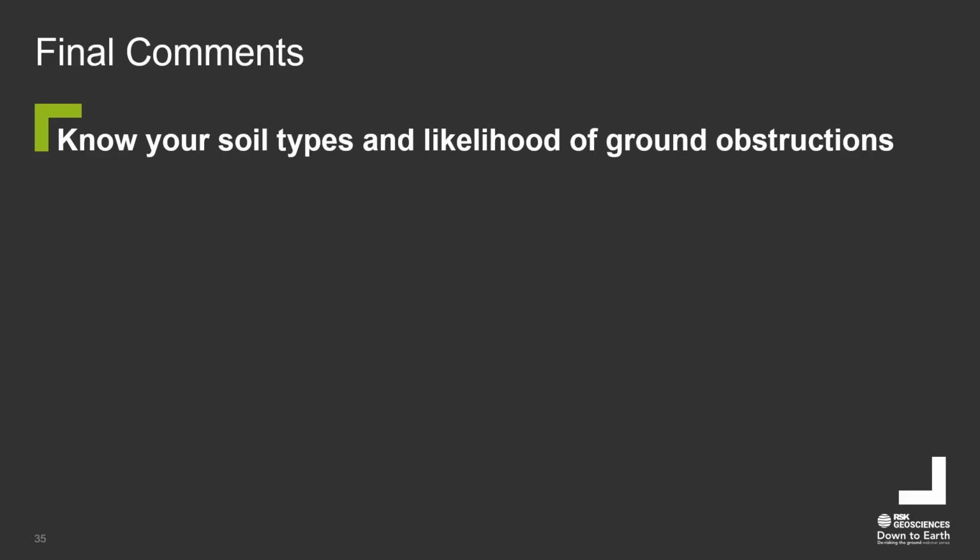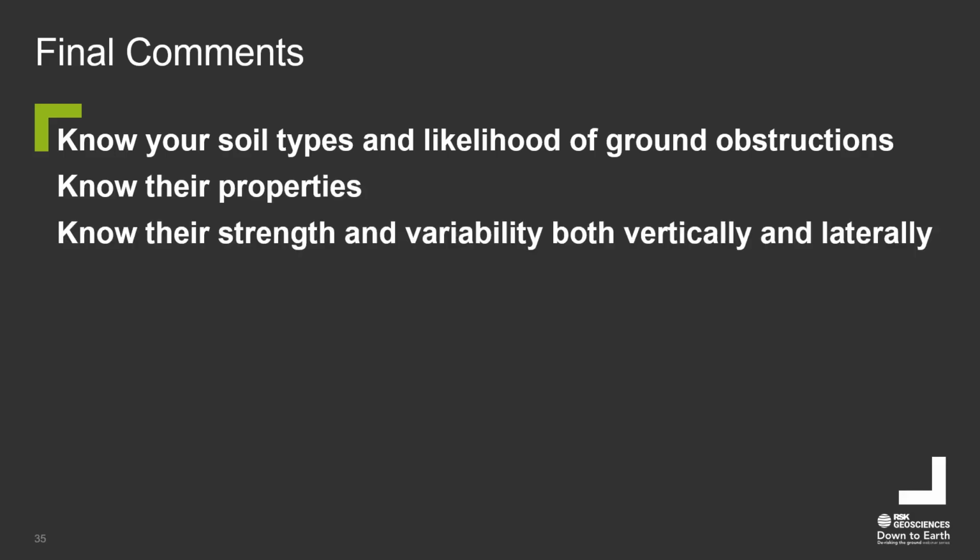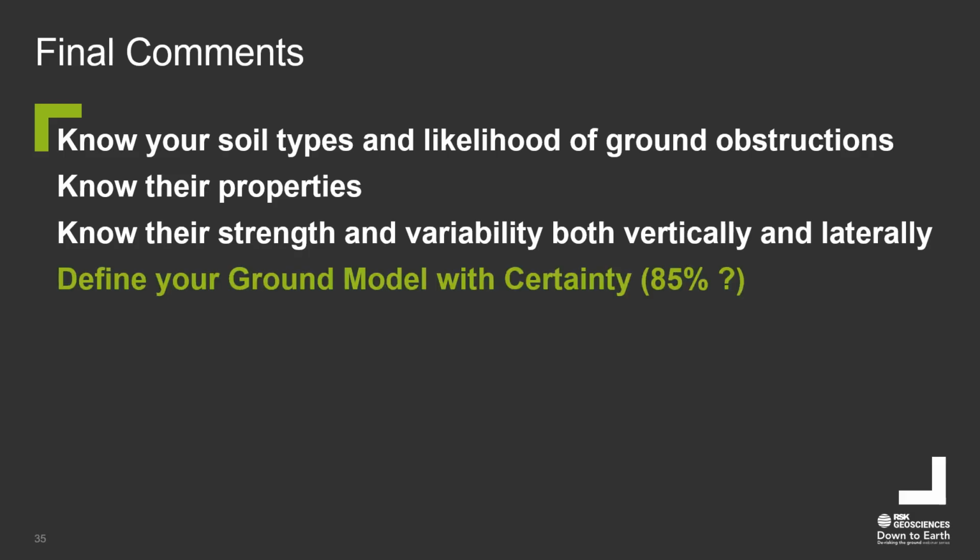Obstructions in the ground are crucial as well with ground investigations and ground improvement techniques, because obstructions will cause big problems for your site ground improvement techniques. Another aspect is properties and details, so we're looking for their strength, variability, and also what their extent is both vertically into the ground and laterally. So how variable are they? Unless we have enough investigation there, we may not know that picture accurately, and therefore we might be a bit too conservative with our design recommendations until we have enough confidence that we can give a more accurate picture, which will then bring down the costs of the schemes.